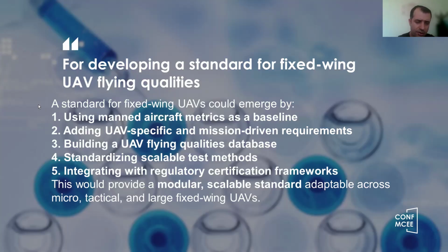First, use aircraft metrics such as natural frequency or damping ratio as initial guidelines. Second, since there is no onboard pilot, metrics should emphasize autonomous stability, robustness to delays, and operator situational awareness. Also, mission-oriented flying qualities should be defined.